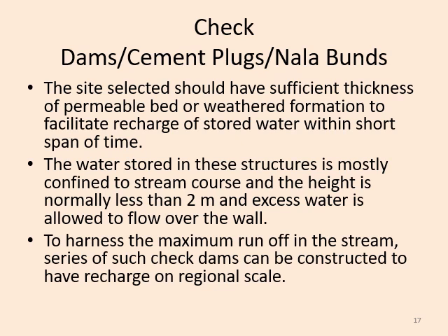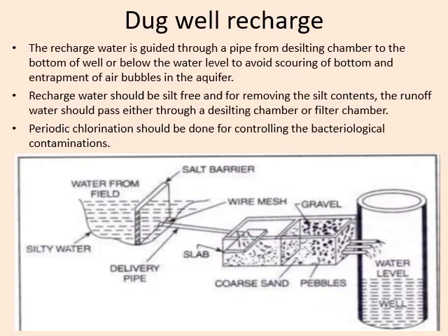We can construct the check dam and recharge the aquifer zone, and also we can take out the stream runoff water on the back side of the check dam or nala bund.